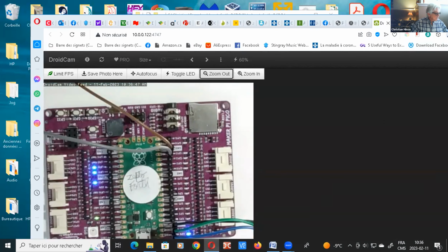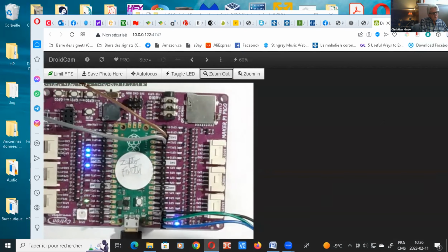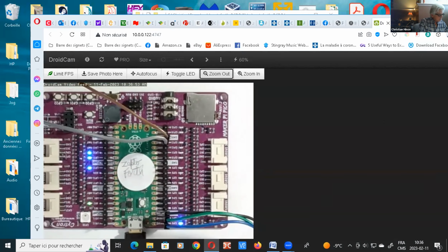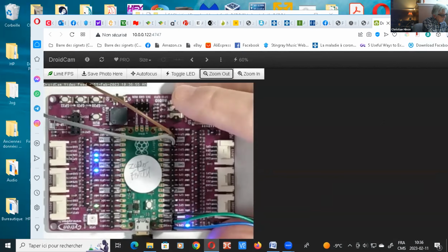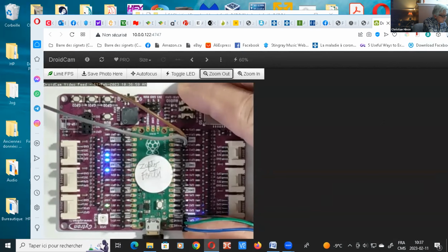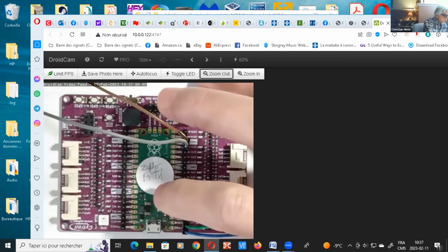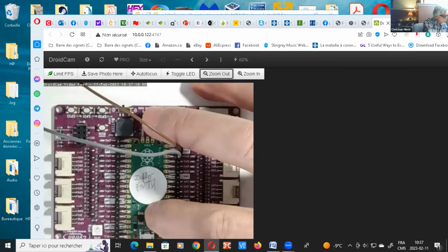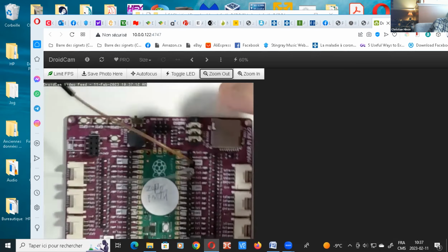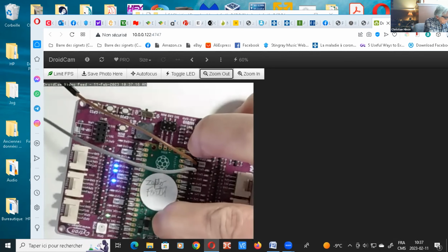Okay. So the whole idea is basically, we'll assume here that the UF2 file has been loaded, but wow, it's not yet loaded. So the whole idea is to disconnect your board, you start with a board that is not powered up. You depress the, how do they call it, boot select button, and you power up.